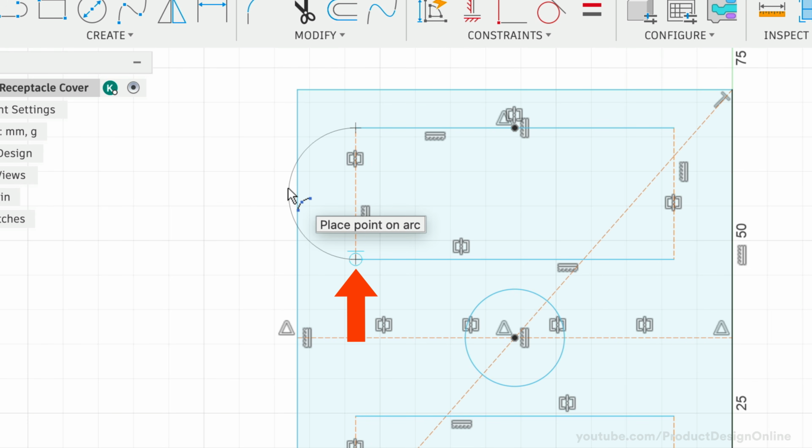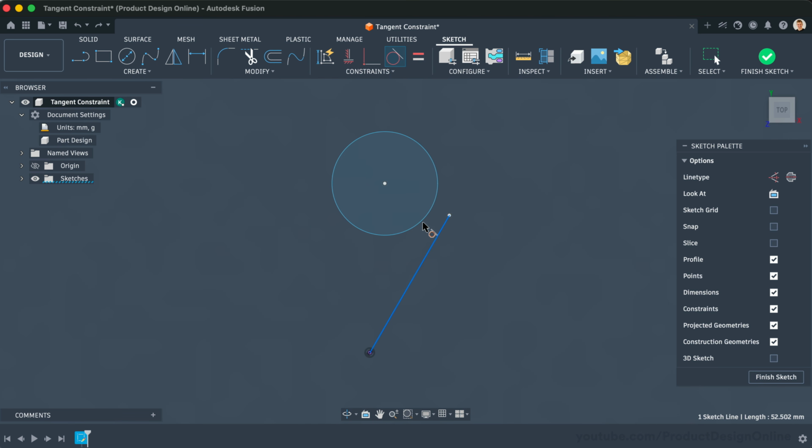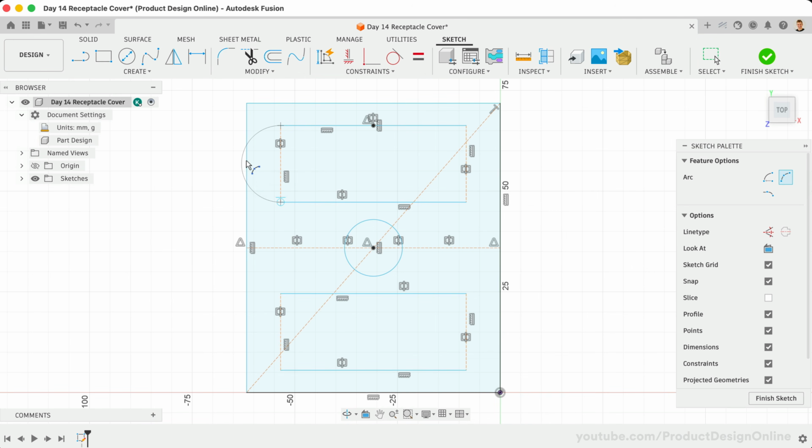Notice a tangent glyph appears, indicating that an automatic tangent constraint will apply here. The tangent constraint forces an arc to remain tangent to connected geometry, resulting in smooth transitions. This matters most when you work on lofted shapes or other complex geometries. In our case, you want to click to place the 3rd point where it does not include the tangent constraints. Then, repeat the 3-point arc for the remaining 3 ends.